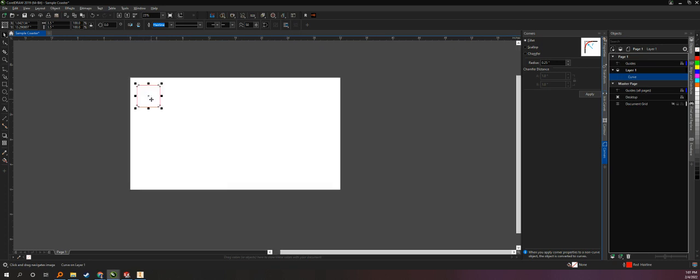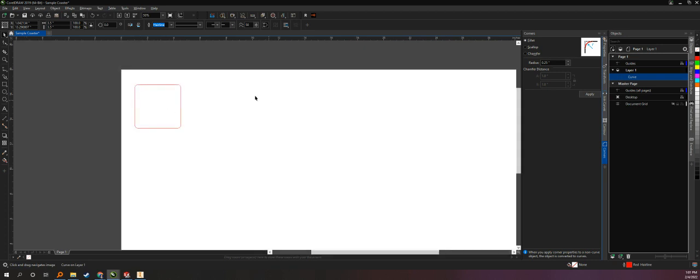So in this one, I'm cutting on the universal laser. The origin will be in the top left, so my offset will be from the top left corner. So I'll click all of my objects that I'm hoping to laser cut, and then I'll reference that point with this top left. And when I click this top left button here, that's referring to this black dot. That's the very top left point of the objects group I've selected.